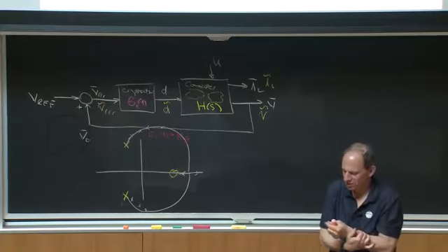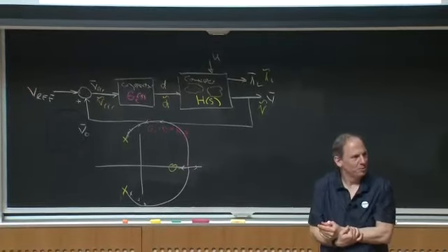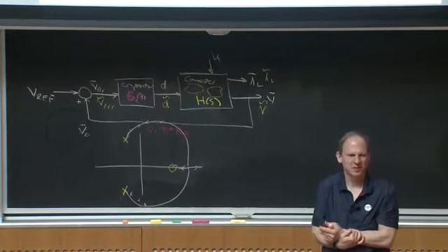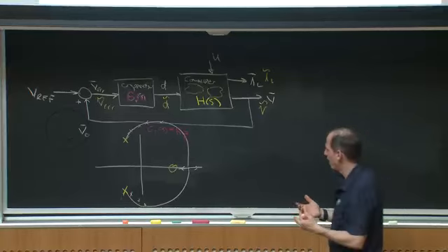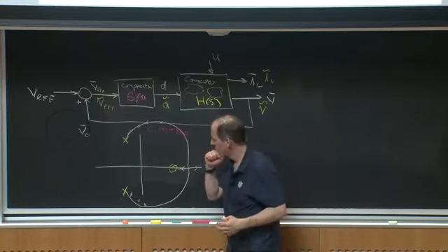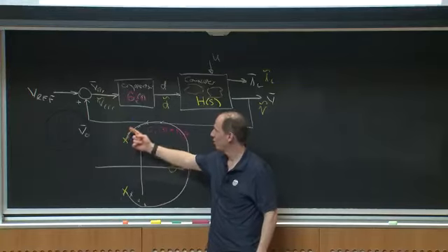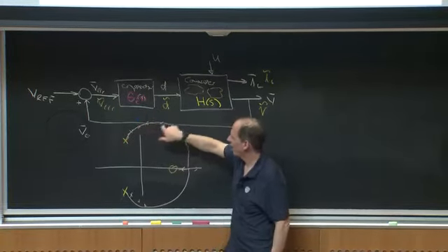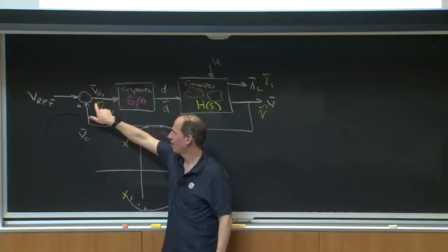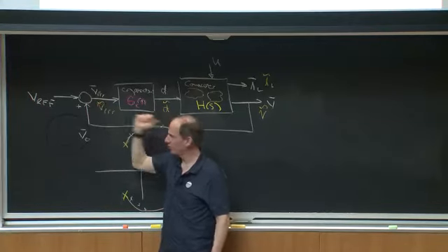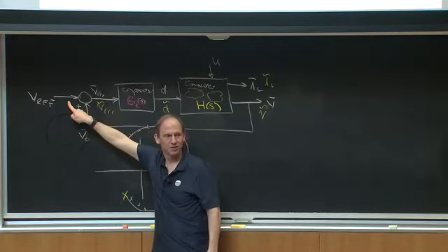Okay. So you wouldn't want to do a proportional compensator on this, just because either it's going to have very bad stability, or what's going to happen is if you limit your gain to be a really low value, that means that you're going to end up living with a pretty big error between the output voltage you're getting and your reference voltage. It's going to be a very droopy output. Okay.